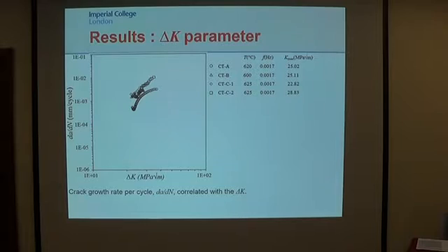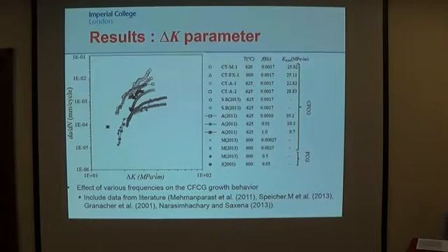So in order to investigate the effects of frequency on the creep fatigue crack growth behavior, I have included the data from the literature. So the data consists of the creep fatigue crack growth behavior up to 1 Hz. And I've also included the pure fatigue crack growth data to examine the frequency effect.